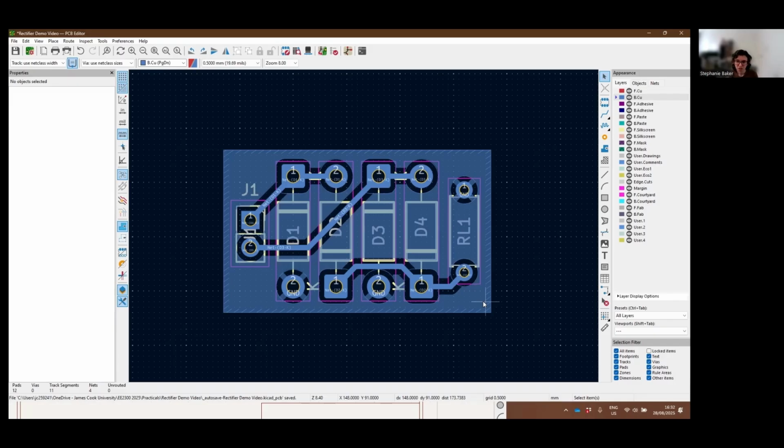Yeah, those are the main advantages in terms of a small, simple board. As you get into bigger and more complex boards, higher frequencies, that sort of thing, then it's also necessary for the signal integrity of things like when you're working with USB or high frequency signals. So yeah, it's just sort of good practice at this point to use this to be able to make your own design easier, but also get those skills in place for when you're building those more advanced boards in future subjects.